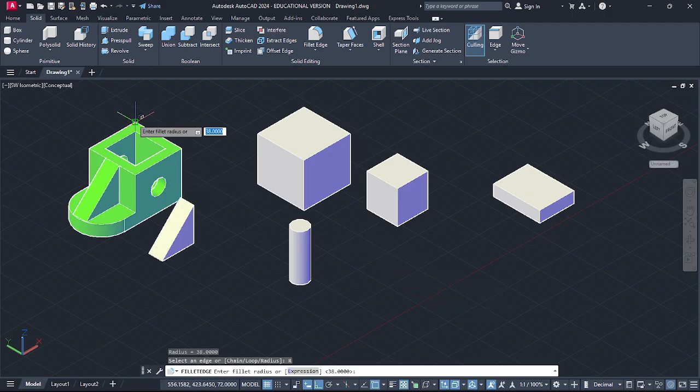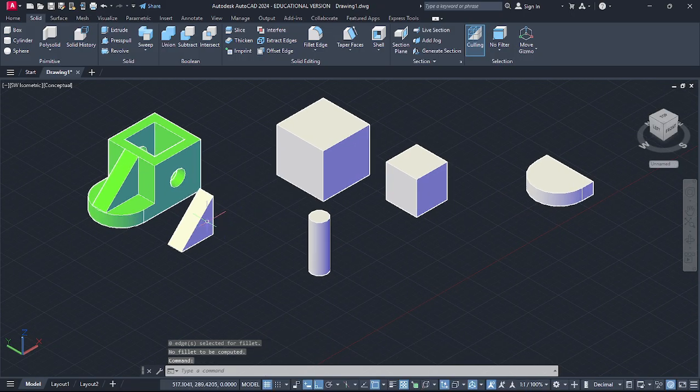When it is totally 76, so by 2, 38. Enter. Select the two corners, first corner, another edge, and enter, double enter. Okay, these are all the primitives. Using these primitives and Boolean operation, make this 3D model.